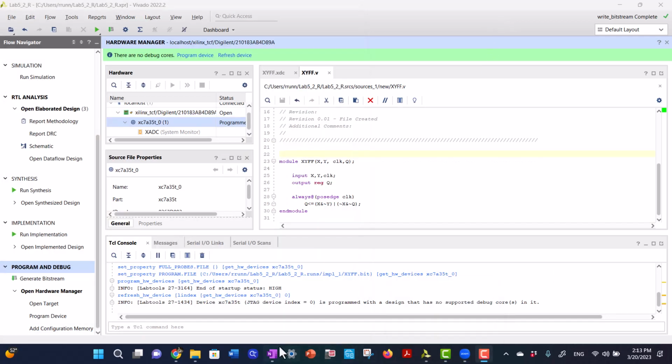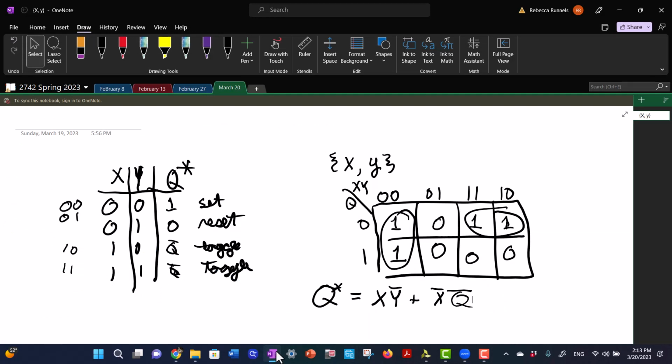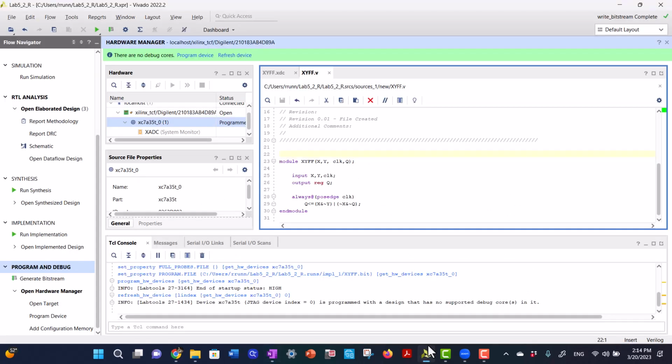Well, at this point, y'all are probably all saying, yeah, you messed up the Karnaugh map again, and it's not X and not Q. It is, so this circle right here, I need to go back to Digital Logic 1, right here, that is X and not Q. That's what it's supposed to be. Now notice these errors I've been making, those are logic errors, so we don't catch them until we actually are running the thing. So take that not out, and I will save it, and then I will pause.